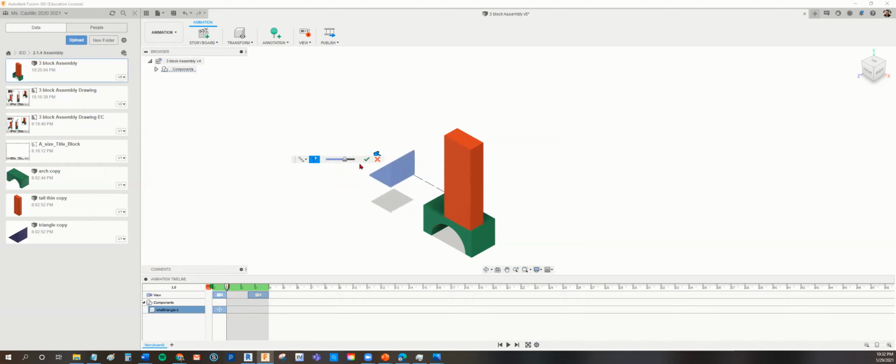See the trail line right here? I'm going to transform it again. Hit transform, manual explode, and this time make sure the trail line is on. This is still sequential. Then I'm going to click on the blue up arrow and toggle back and forth. It's going to go up that far. Hit OK. If you notice, it's already putting the sequential animations onto the timeline here at the bottom.